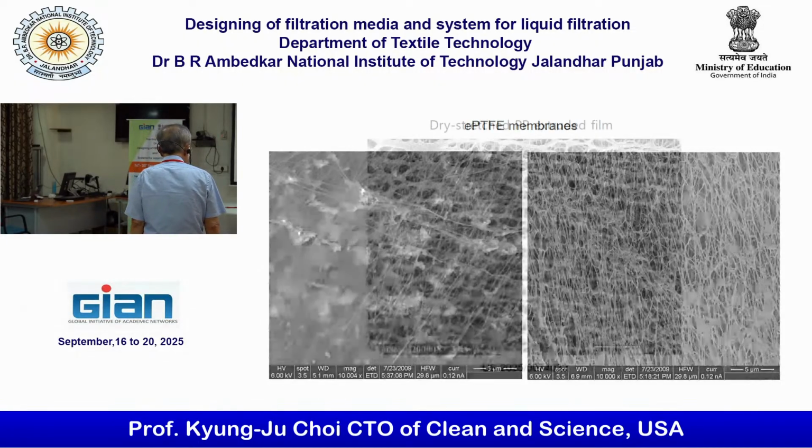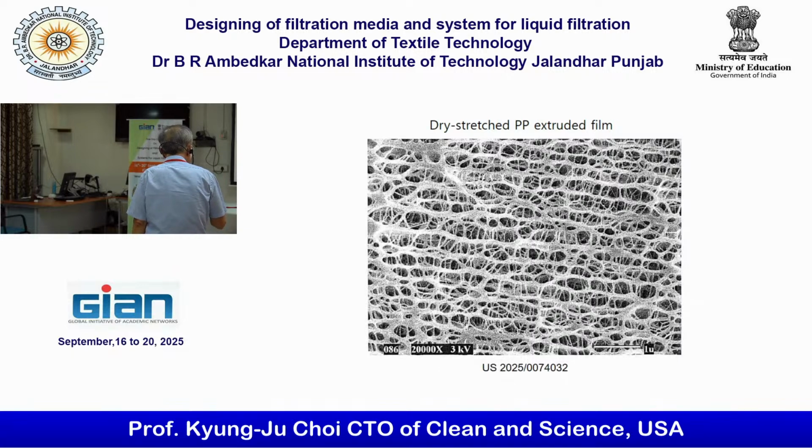Okay, this is commercially available: a dry stretched polypropylene extruded film. Quality-wise, it's a little bit of an issue, but it is available. But this one, the porosity is a lot. So normally for EPTFE, the porosity is more than 95%. This one is around 60 or 70%.